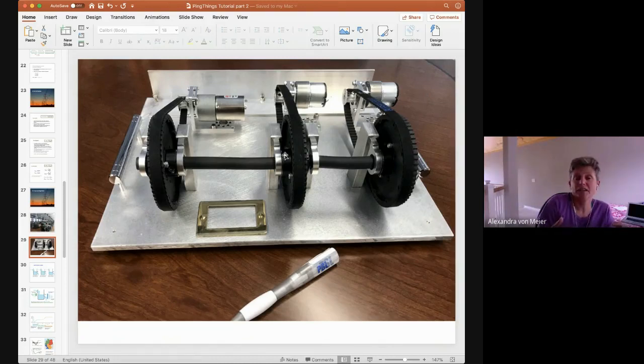The voltage is going to be a little bit behind. And depending on the stiffness of the shaft, and that stiffness is the electrical impedance in the grid, you can also appreciate that if there's too much twist, or too much soft rubber, or the shaft is too long, then you're going to lose synchronicity between and among the devices.